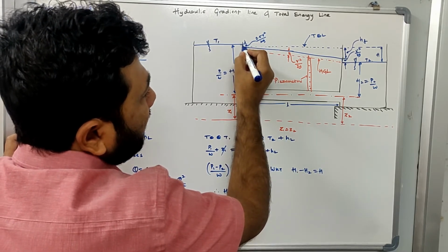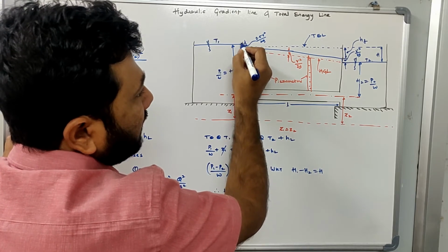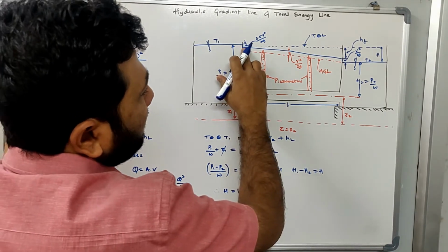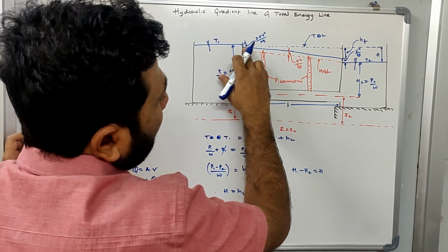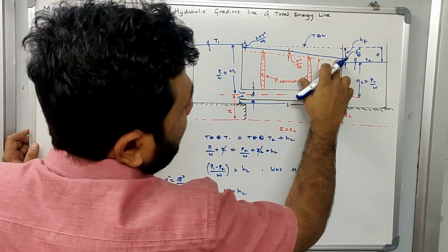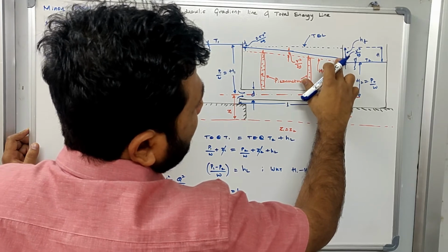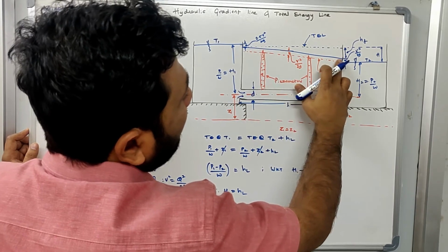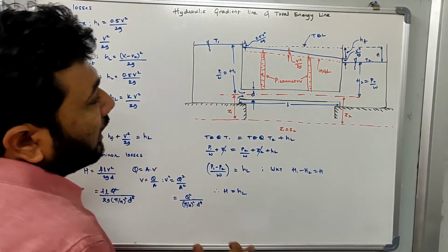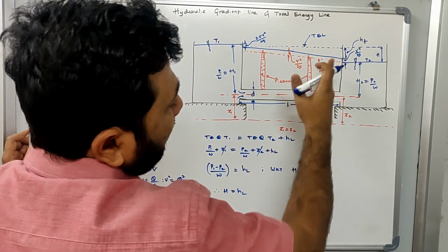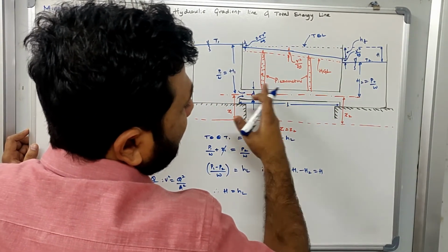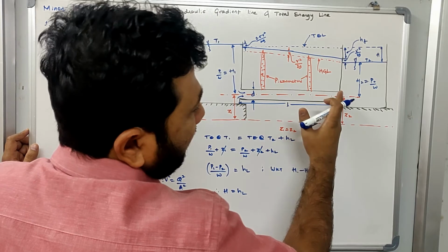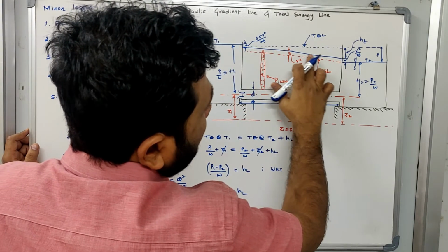Now see, there is a sudden dip in the line. This sudden dip is because of entrance loss. The energy is lost due to entrance. Now, this is a linearly reducing energy line. What is this linearly reducing line representing? This blue line. Don't focus on the red dotted line that I have drawn, focus on the blue line. This is representing how the energy is lost linearly with respect to the friction exerted on the flowing water. So this frictional resistance reduces the energy gradually.